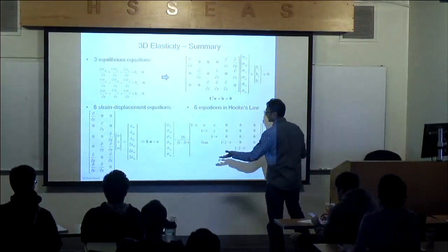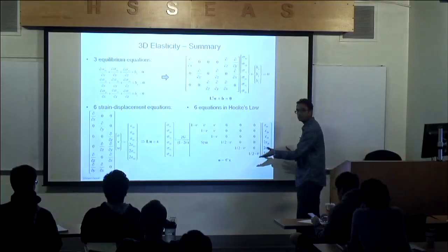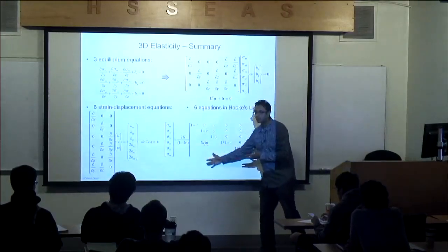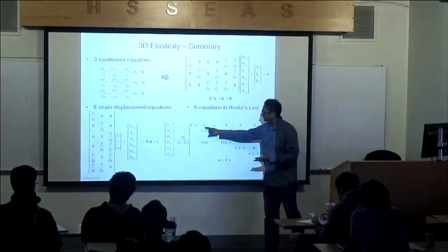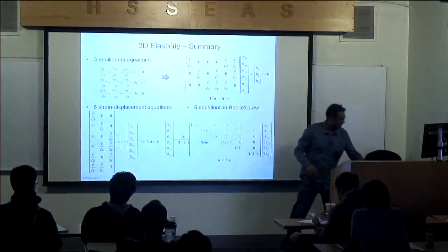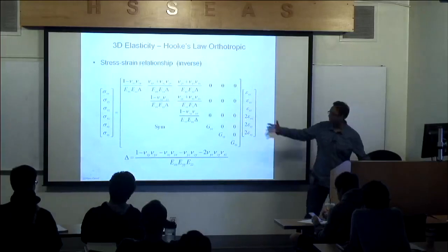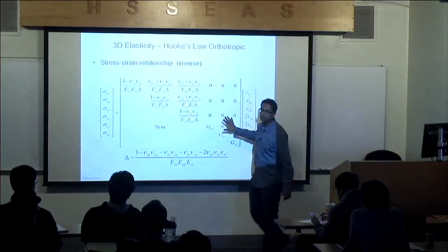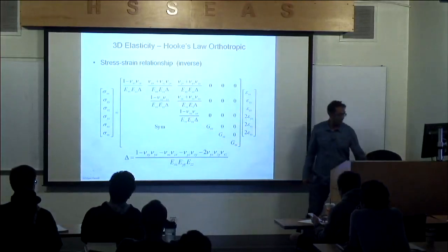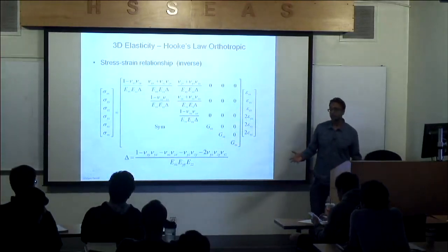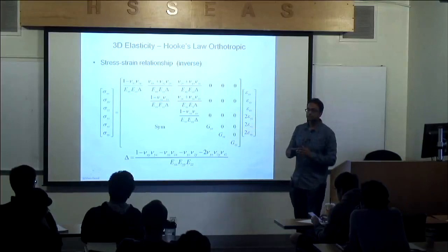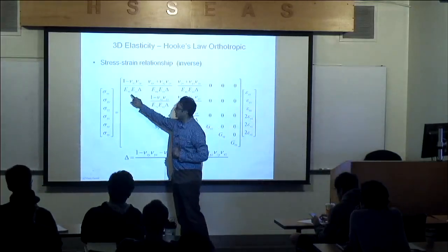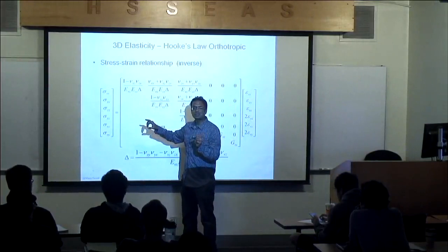We also have this full constitutive behavior for 3D, which is isotropic here, but you can make it composite. You can use a fully populated composite material given here. So if you're working with composites, you can fully populate this, and Abaqus can handle it. So the way Abaqus handles this matrix is that you define, or in Nastran, it's a MAT9 card.